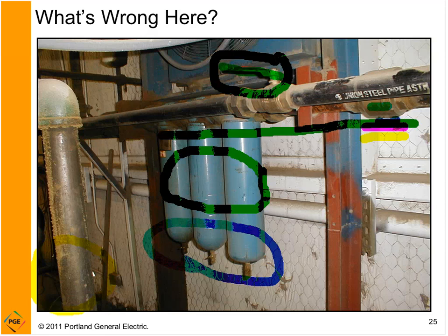This, by the way, is probably a check valve, which is another device which also creates a little bit of a pressure drop, but that's not the point. The point is that the filters are allowing air to flow through this back line, and then the bypass line is right here. It's cracked open. I'm allowing some of the air to get by so I get pressure downstream.